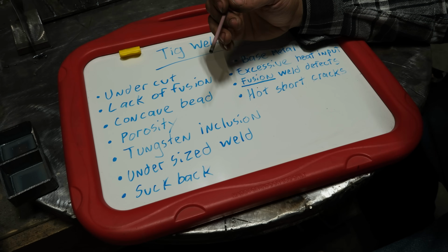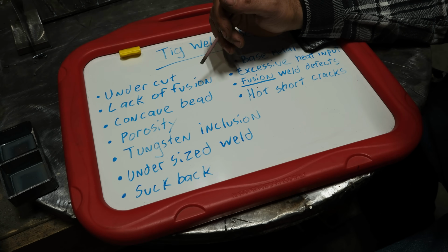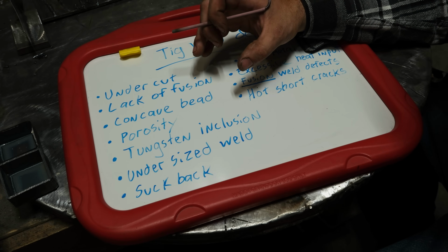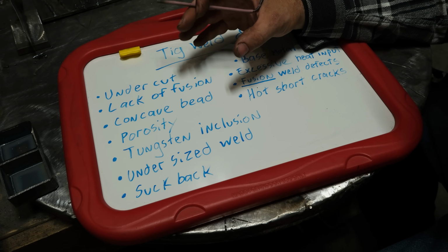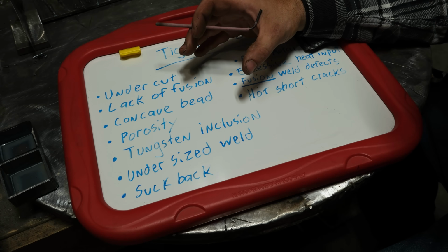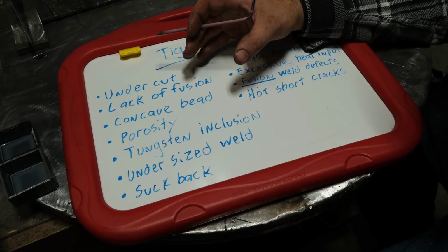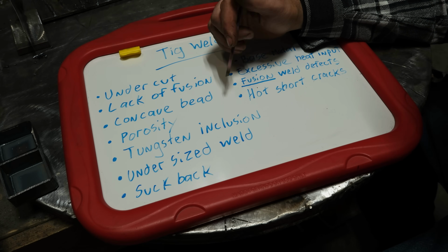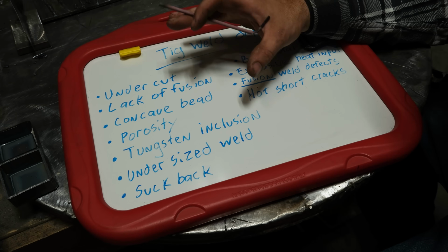Now, TIG welding is very strong. The welds are very strong, and they can achieve high levels of fusion despite not putting down much metal. And that's where the strength is, technically, for the size. Well, I'll put it to you this way: stick and MIG cannot produce as small a weld as TIG that has any fusion on thicker material. And that's just the nature of TIG, because it's a high fusion process and you control the filler. You can achieve welds that no other process, other than maybe laser or electron beam, can produce.